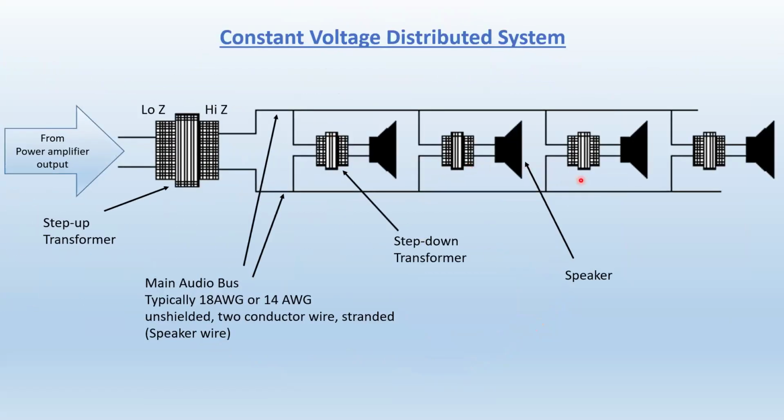So you get the taps. Now, let's say you set all the speakers at 1 watt. All these 2, you choose the black, which is common, and because different companies produce different transformers in a different way, some of them have different colors, but they put a little legend, a little sticker on the transformer for you to see what's what. Some of them don't have wires, they just have spade taps, and you can just connect that. Every transformer looks different, but it's the same idea how it works.